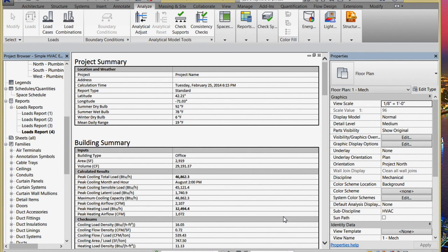And what's happening to capacity? The airflow is 1,000. The cooling capacity, latent load. Airflow, 2107. So what's the message? It really is pretty sensitive. As you refine your building design, you'll start narrowing in on something that's pretty close. Even from 38 to 46 is not nearly as bad as the nearly 3 times, or 2.5 times, we saw before.